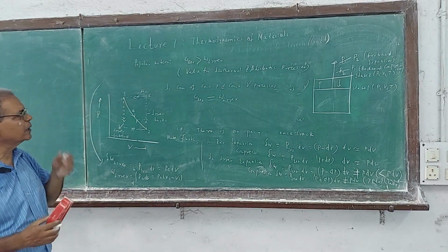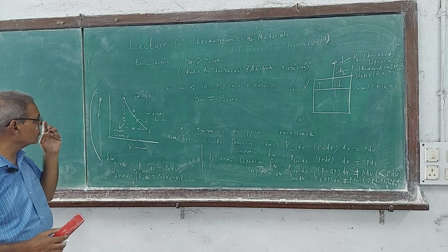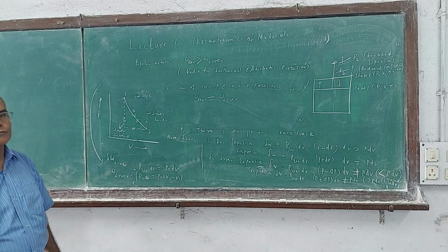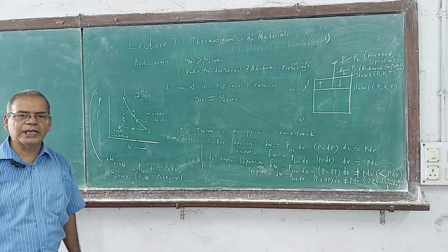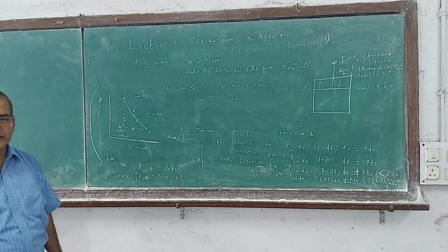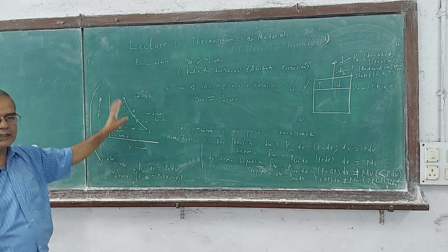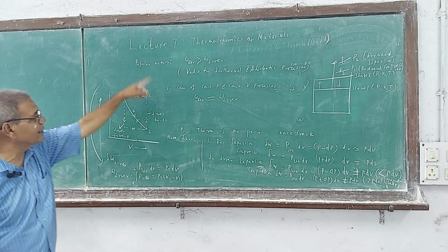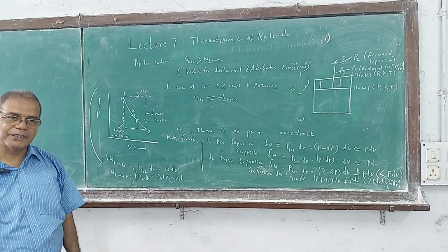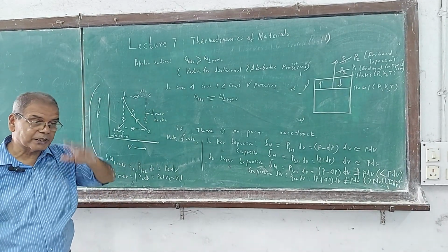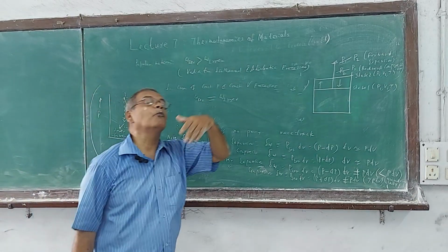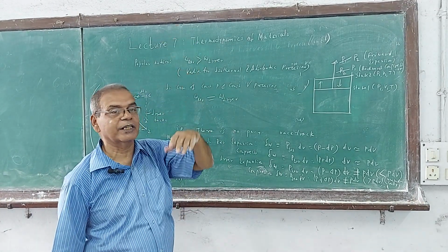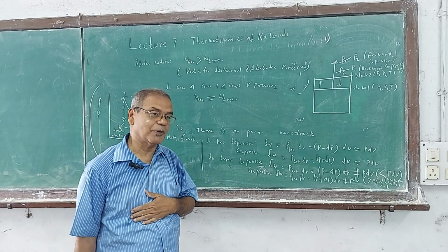Over this part I wanted to tell you about reversible work. So there are three ways you can show that reversible work is greater than irreversible work. One is graphically, the area under the curve. Another is analytically, which I have explained and established. Third is conceptually: in expansion, where is the opposition greater? In reversible work.